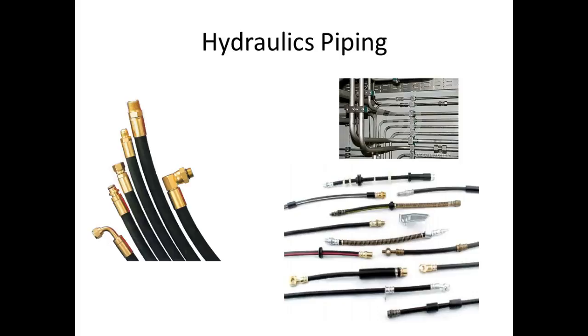Your compressor doesn't see cold. It just sees what it gets back, right? Where does the cold come from? When it runs through the compressor, it takes a gas and puts it under so much pressure that it converts it into a liquid. The problem with gas at extremely high pressure is that the more pressure you put on a gas, sooner or later it's going to try to change into a liquid. So your air conditioner sees a gas, and then it takes that gas and converts it into a liquid.